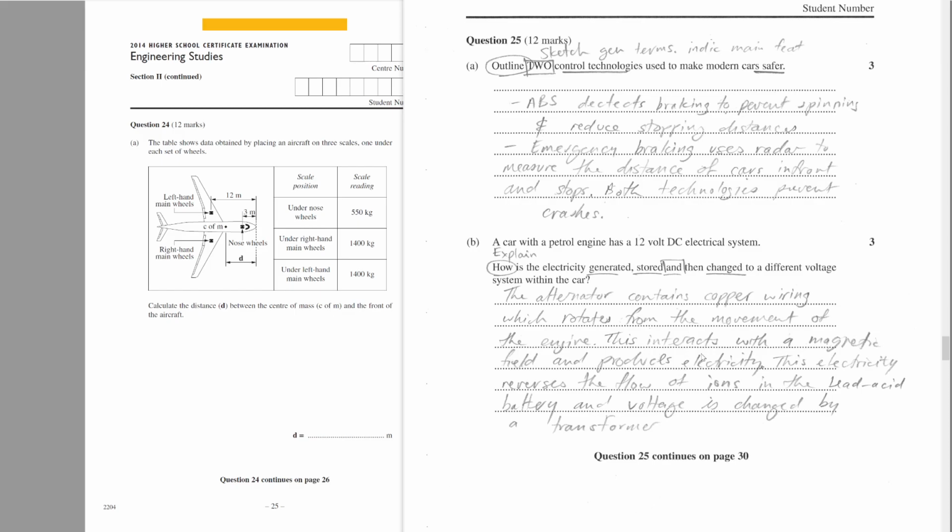Okay, so the alternator is a small generator in the car. All right, if you wrote small generator. Now, I said here it contains copper wiring which rotates. That is not true. The copper wiring does not rotate. The copper wiring is stationary. The magnet rotates. And movement plus magnets equals electricity. Anyway, you probably even write that and get a mark, actually. The alternator contains moving magnets. They produce electricity. Boom. I then spent 2 sentences doing that. Right? I could have tried to write a little bit shorter.